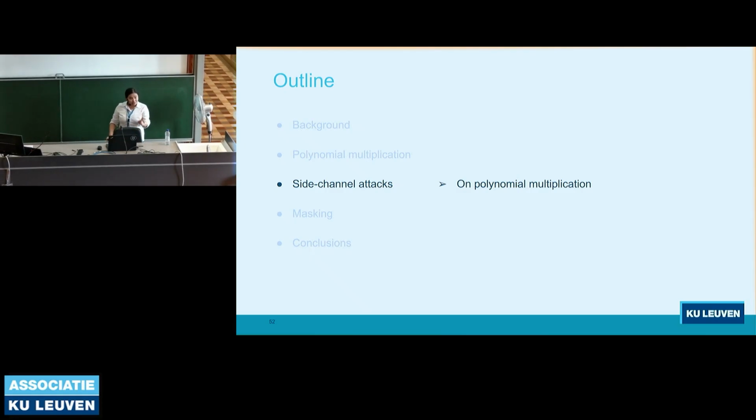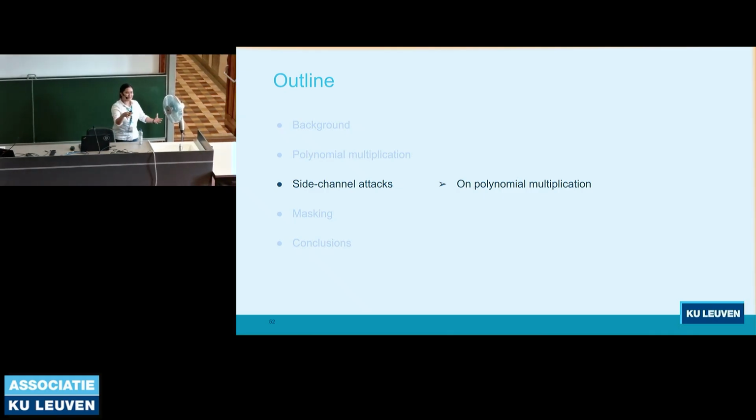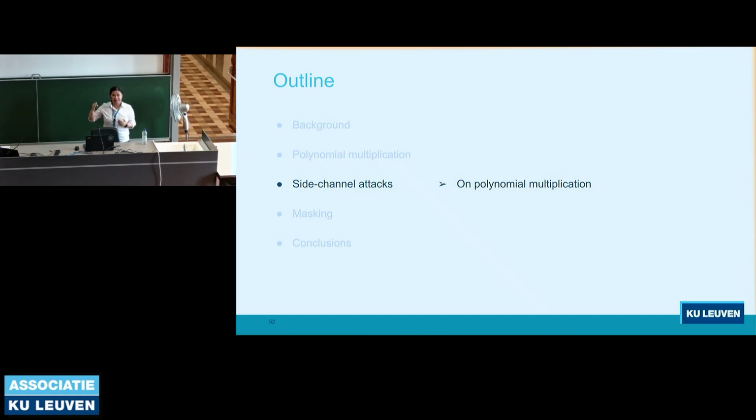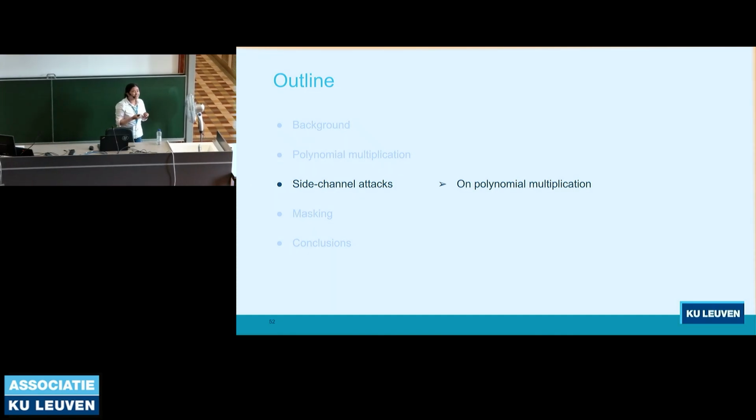Conversely, you can also use NTT for a power of 2 modulus, by increasing your prime number and keeping everything in between that big prime. That does reduce complexity up to some point, but it incurs a huge area. So it's a good choice, but not the best one, I would say.